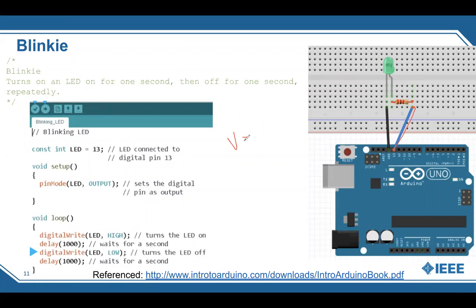Because if we have voltage equals I times R, which is Ohm's law, you might not know this yet if you're a beginner, but if we supply a specific amount of current and we have no resistance, it's going to be infinite and it's going to result in an error, because we have to maintain this. So we don't want any error values to occur. So we're going to insert some resistance. When we supply the current, it's going to give us a number for our voltage, and we're not going to have an error message or infinite current running through and causing potential damage to our LED.